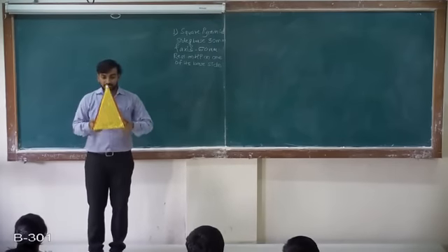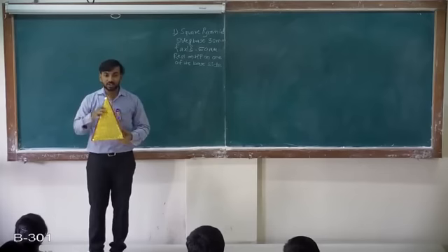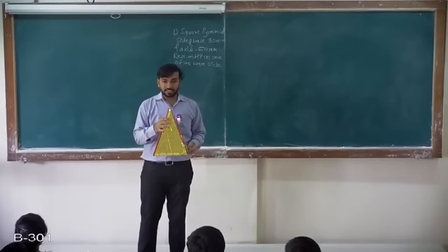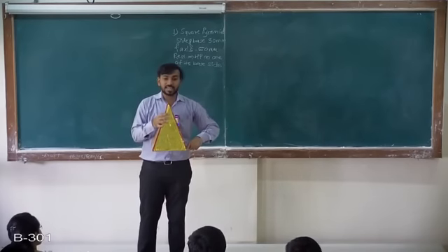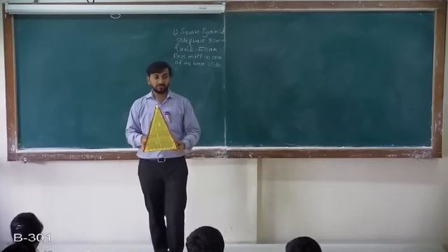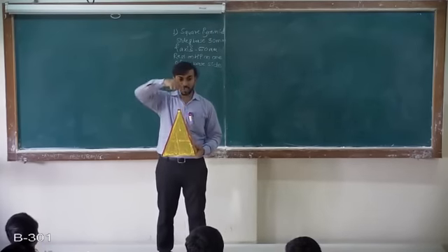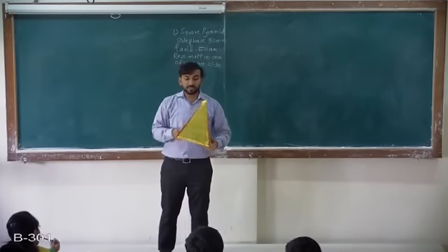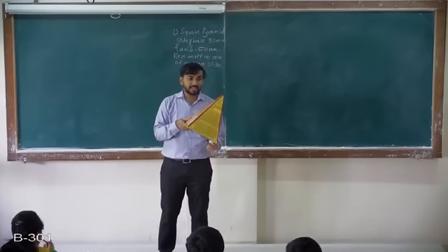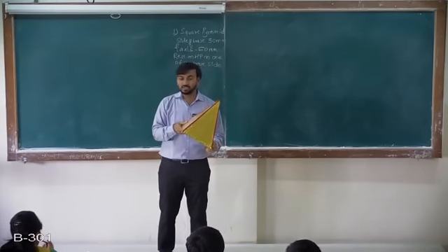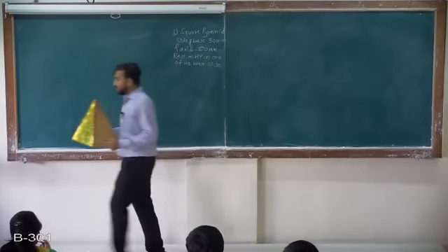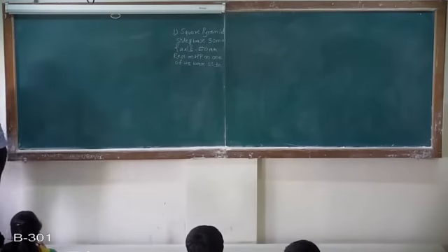So for the first stage I will draw with the given dimensions, resting on a side. We are going to follow the resting side on the right. Let's say this side is AB. So AB is the resting side. I will draw like this, the first stage front view as well as top view. In the second stage it may be inclined like this because we have the resting side on the right. So we are keeping this side as the resting parameter, right. The second stage inclination will be with HP according to the given value. So first I will draw the first stage.